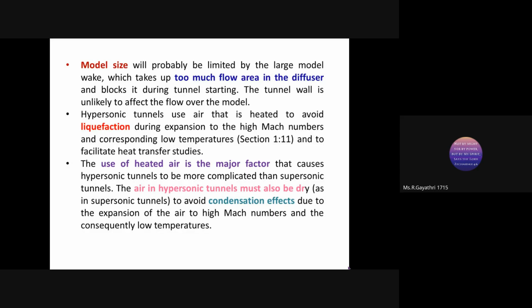The model size will probably be limited by the large model wake, which takes up too much flow area in the diffuser and blocks it during the tunnel starting. Already we kept the larger model. We can see the wake also, so it can block the flow while running the tunnel.